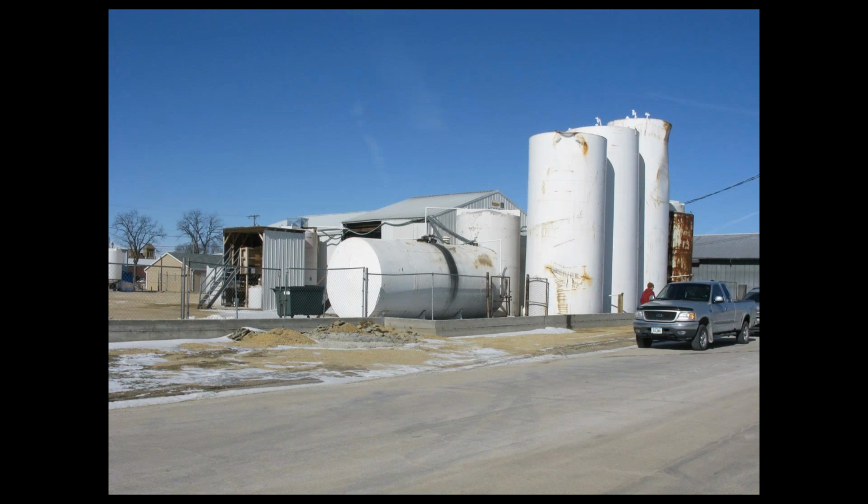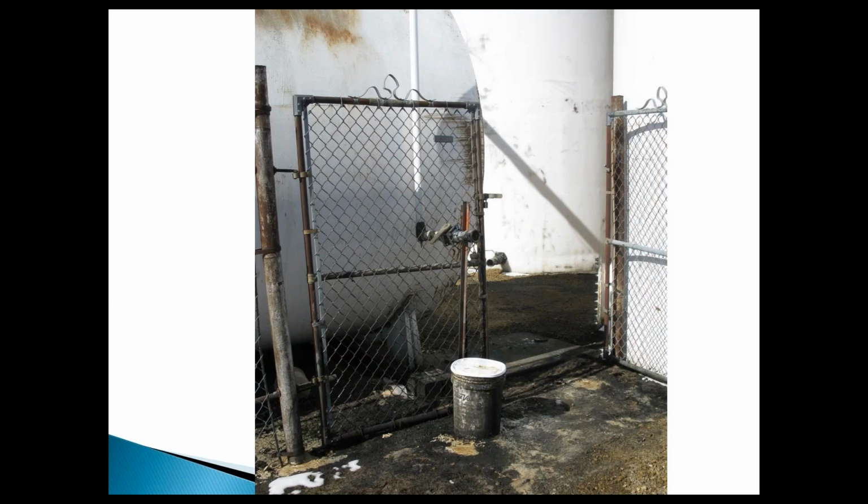Well, number one, the middle tank has had overfills. The other tanks on the side appear to have venting problems, and they've collapsed. They've sucked them in, and that tank at the end, I would ask, how many times have you inspected that? And then as a code official, I'd be looking at, and you can barely see it, I think we have some close-ups, but if you look at that transfer piping, it's held up by a piece of wood. It's a flammable combustible material. You don't want that. This is a big signal for us.